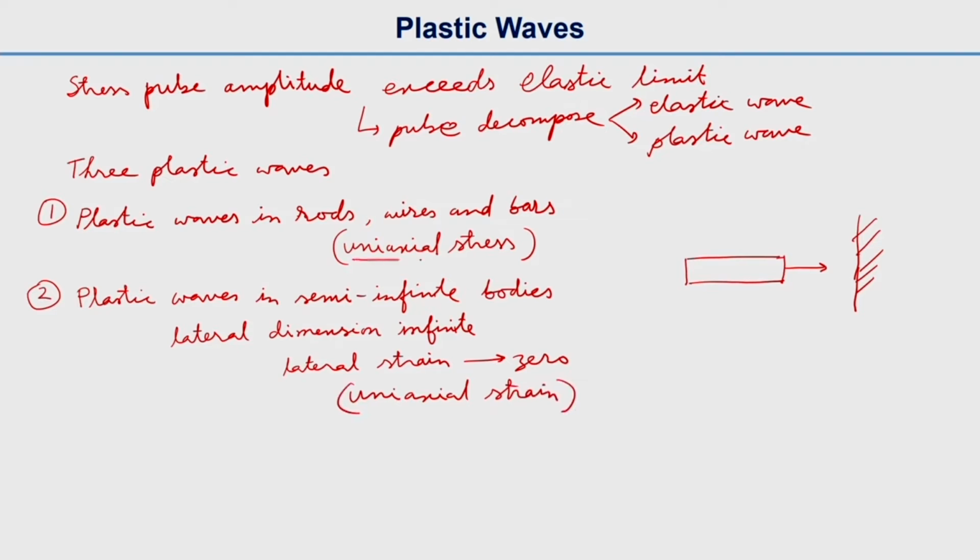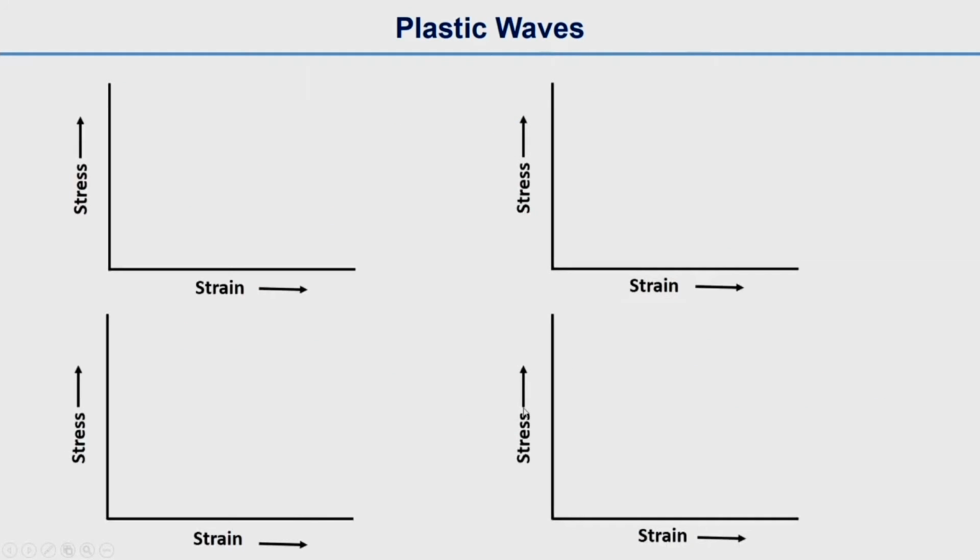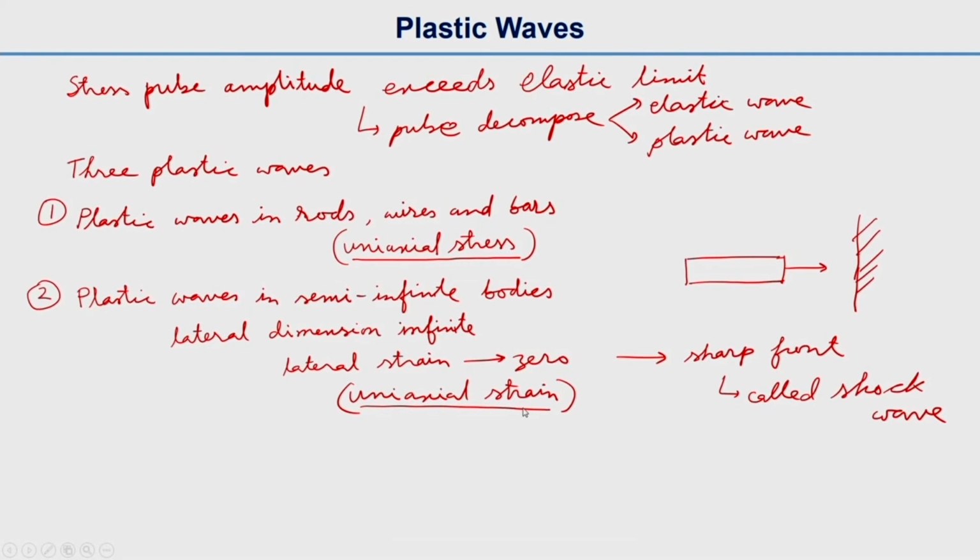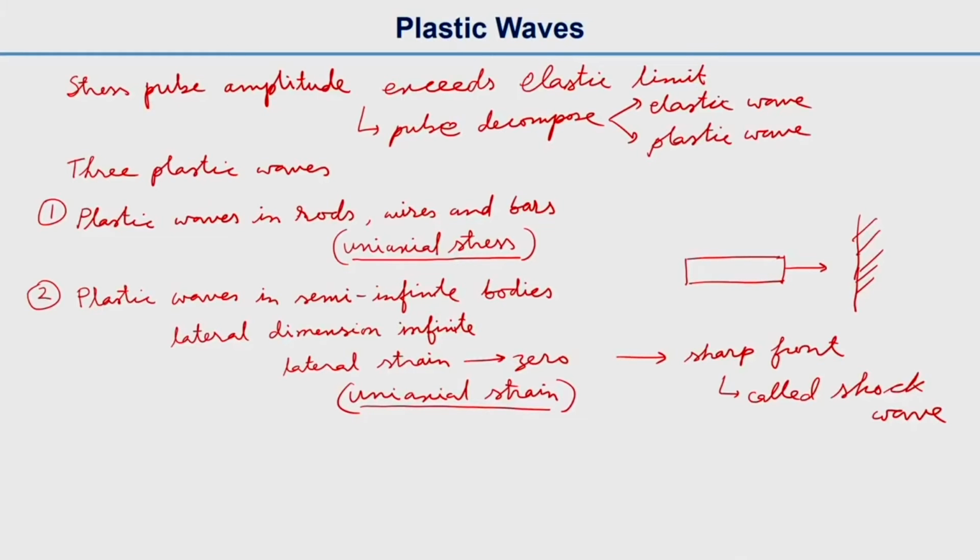So the earlier case we had uniaxial stress and here it is uniaxial strain, and this will lead to a very sharp wave front, and that is called a shock wave.